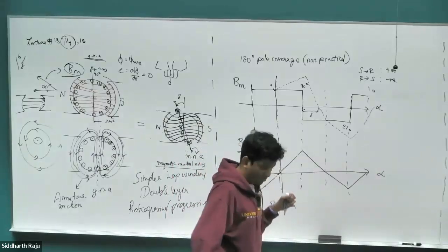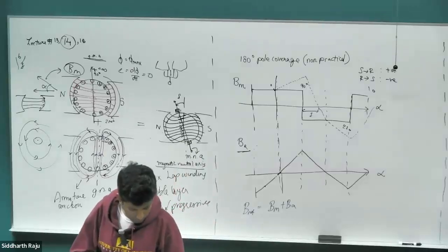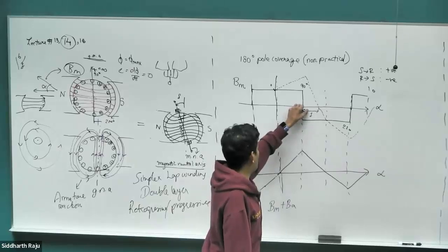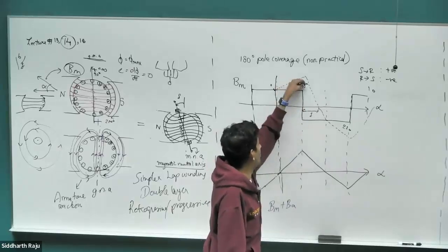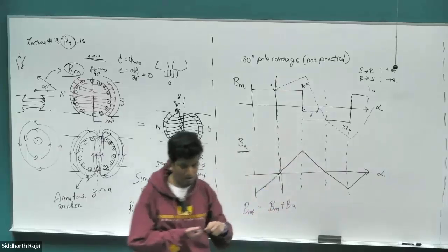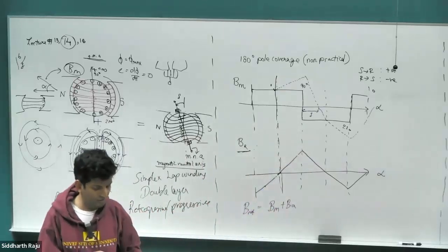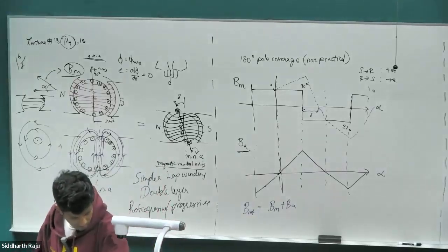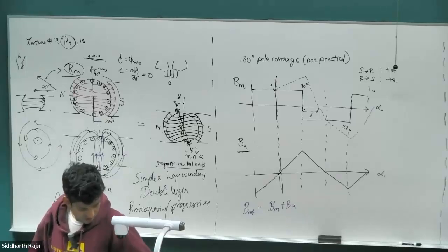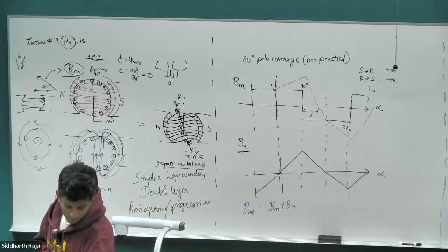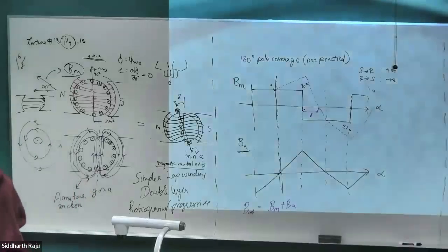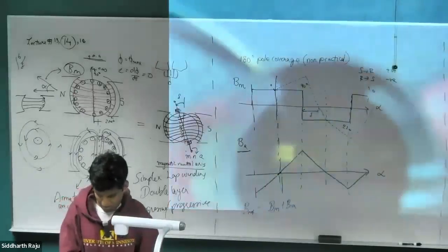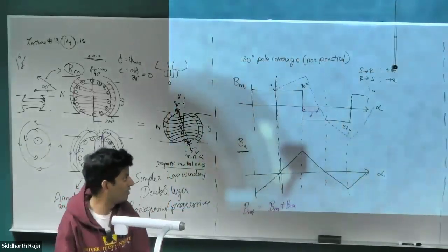So there is a nice solution in practical motors. What we do is we try to reduce the effect of this armature reaction at this angle, where we want the commutation to happen. We want to reduce the effect of the armature current on the magnetic field that's created in the air gap. So one way we achieve that is by making sure our poles do not have a full 180-degree coverage.